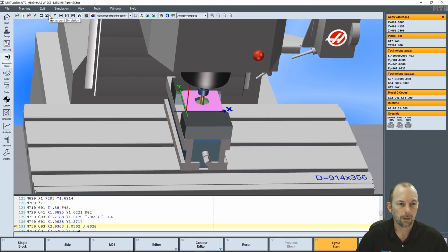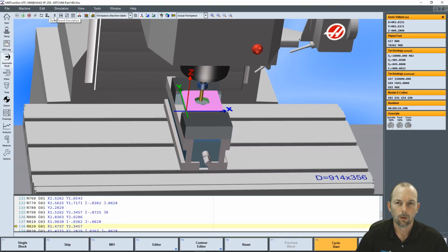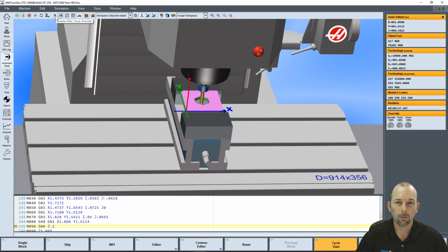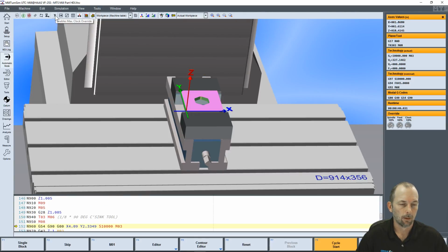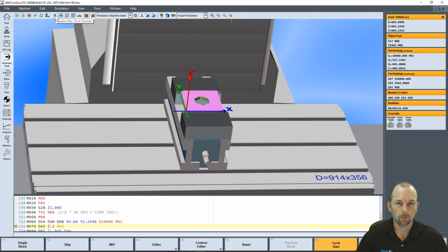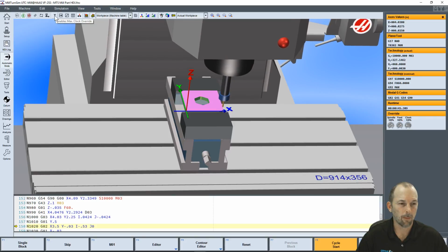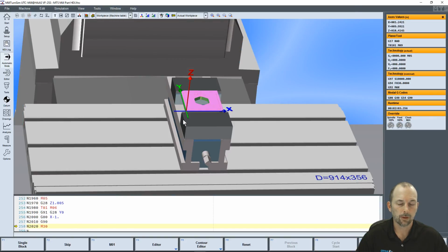Background simulation we'll detail in a later video. The T, the test mode, enables max clock override. So what that means is when you depress the T or the max clock override, it runs a simulation as fast as your computer is capable of running it. You see it sets our clock override to maximum. With it deselected, we have a clock override set at 120% right now.